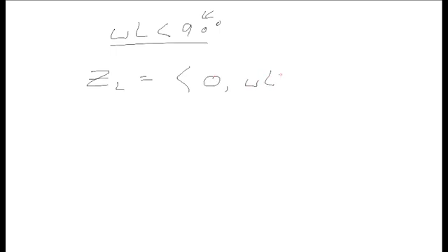Let's take a look. That impedance was given as omega times the inductance, angle 90 degrees. Remember, phasors are just complex numbers. So let's see what complex number this becomes. Well, I might call this ZL, the impedance of the inductor. And this is an impedance that is aligned with 90 degrees, the complex axis, which means as a vector, it's 0, omega L, or as a complex number, it's j omega L.